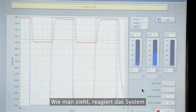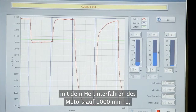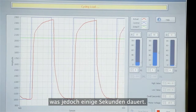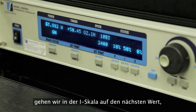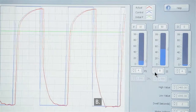You'll see that the system response is bringing the motor down to 1000 RPM, but it's taking a couple of seconds to get there. So in order to speed up that response, we'll change our I scale to the next value, B.